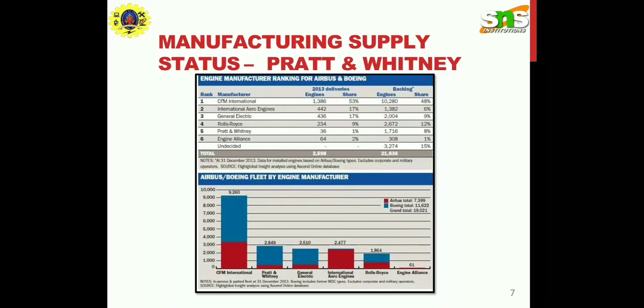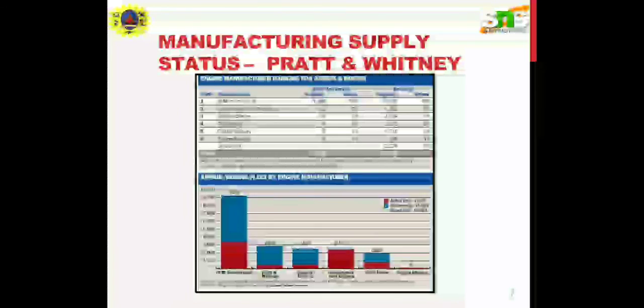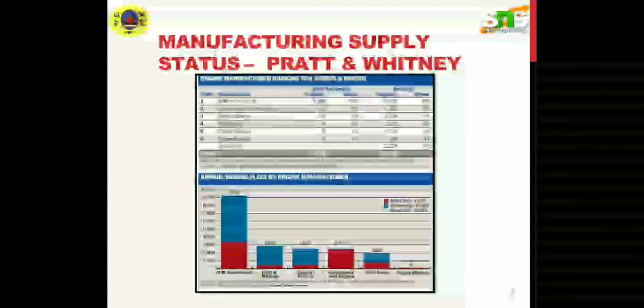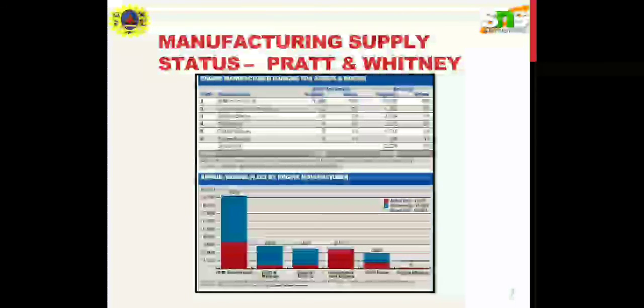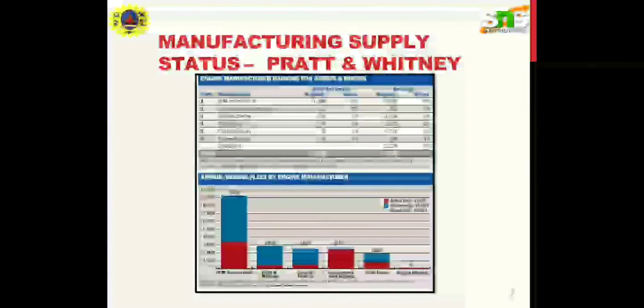Velocity will decrease over the rotor. Here the Pelton wheel is an impulse design. So reaction turbo machines operate by reacting the flow of a fluid through airfoil shaped rotor and stator blades. The velocity of the fluid through the set of blades increases slightly as it passes from rotor to stator and vice versa, and the velocity decreases through the set of blades.